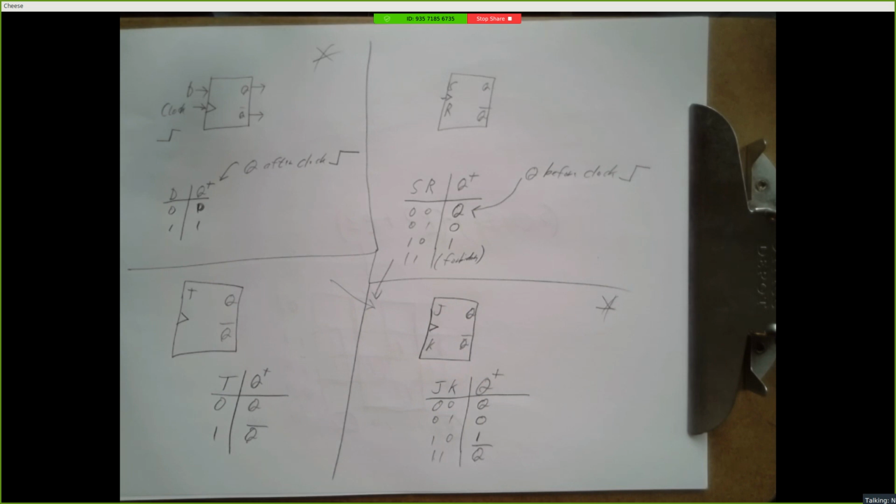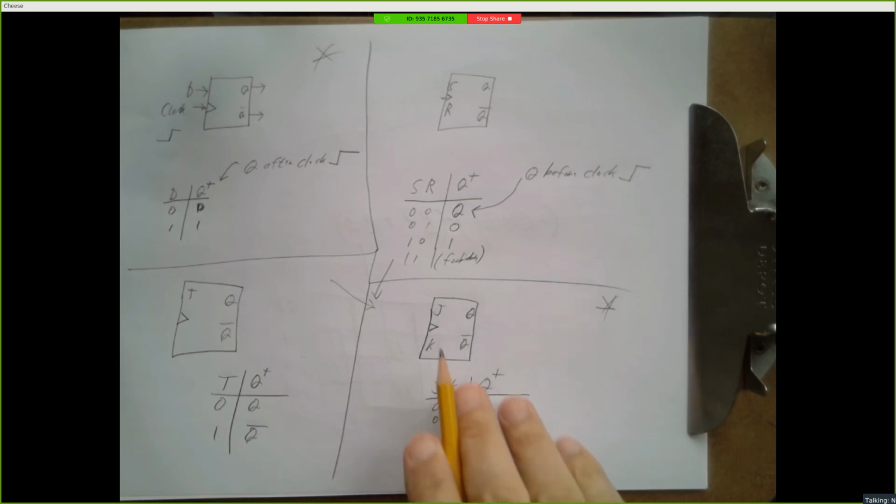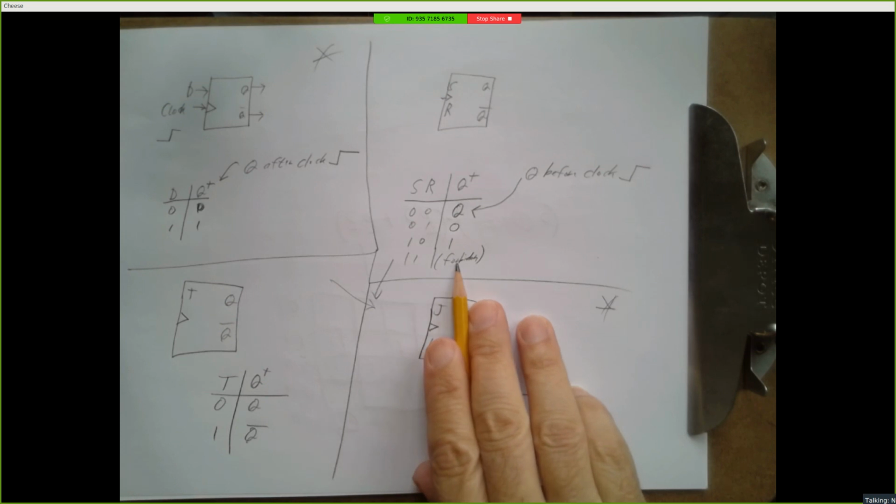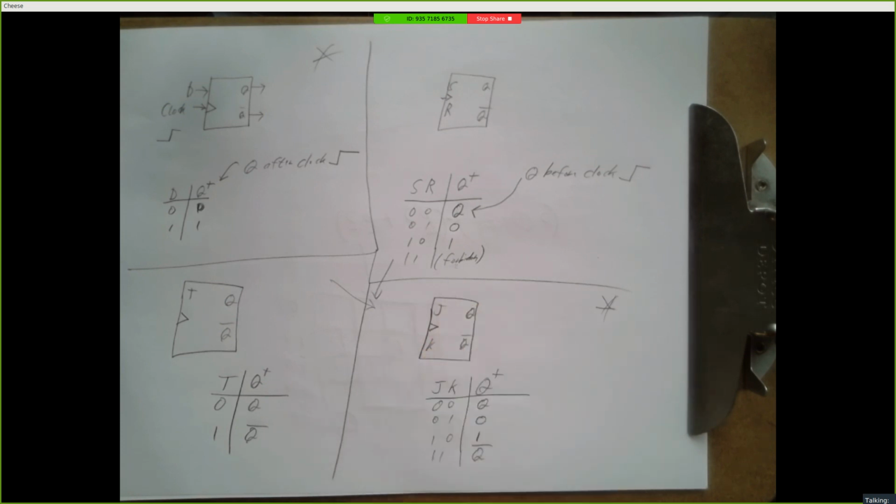I simulated one of the homework circuits, and when both inputs were on, the output flashed on and off rapidly. Yeah, so that's probably an undefined state or a forbidden state. Sometimes that can come from what's called a race condition, which we looked at a little bit, where if the inputs change at just the wrong time, you can get an output that's unstable. In reality, for an SR, depending on how it's built, it'll either give you a 0 or a 1 in this state, usually. But for some of the other homework circuits, yeah, you could get that undefined state. That's probably what you were seeing.